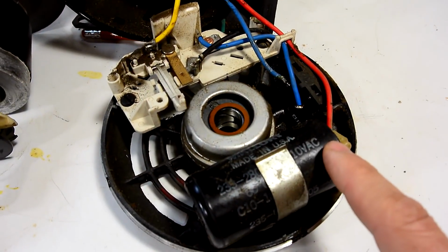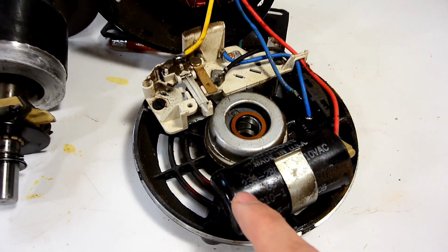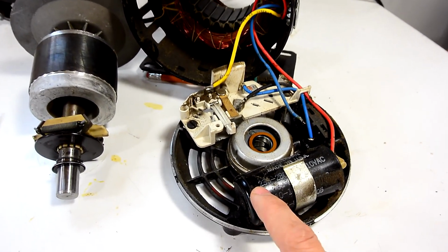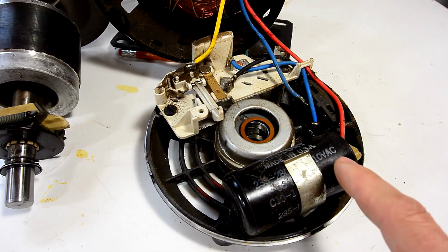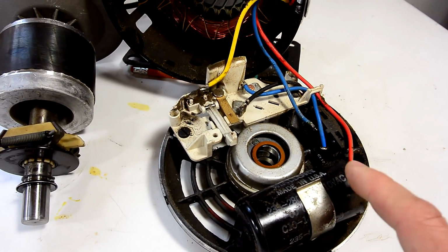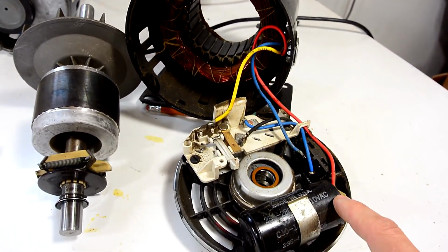So if the starter winding helps to create a rotating magnetic field to spin up the motor, why disconnect it once the motor is actually up to speed? The whole phase shifting the starter winding with a capacitor is not as elegant as it would sound. The size of the capacitor very much depends on the expected load of the motor, and if we just connect it briefly temporarily at the start, it doesn't matter if it's a little bit inefficient or the wrong size, because we won't leave it engaged.